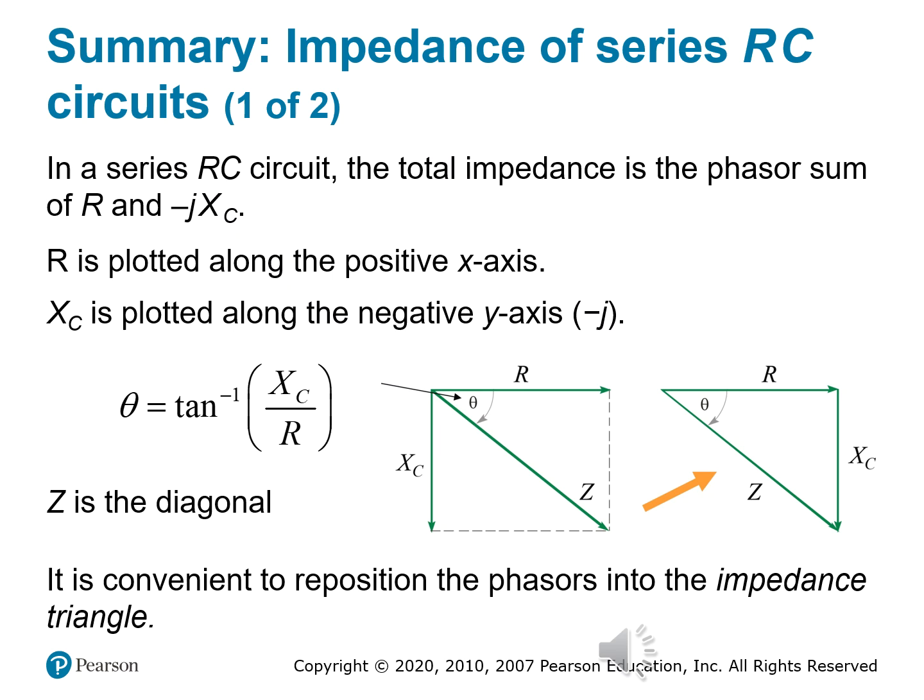Compare that to inductors. If you've been following along, this triangle might feel familiar. In an RL circuit, the inductor's plus jX sub L phasor went upward, and the current lagged. Here in the RC world, the phasor points downward, and the current leads. So it's a visual mirror, a kind of B-side of the inductor story. So a negative B-side of the inductor story.